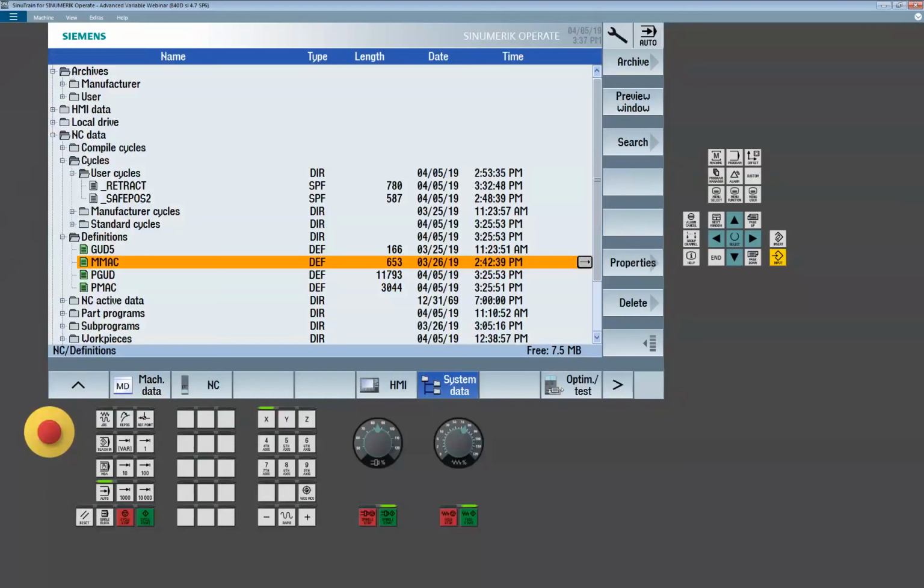Okay, if you reset while in a PROC subroutine, will save on the PROC line, will the original G-code functions be reinstated? No. The easy answer is they're asking that if we're in the middle of the cycle that we just wrote and we hit the reset button, what happens? It's going to maintain the commands at that point in time.